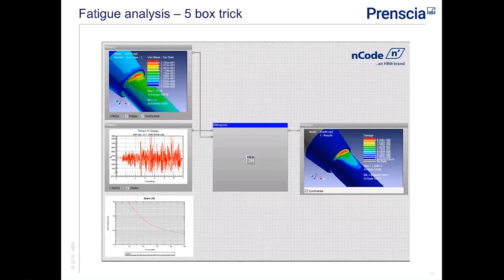And then, given those 3 types of input information, we can carry out a fatigue analysis, and then typically we look at the results in terms of contour plots of damage or life or tables. So this kind of process is pretty well established and trusted for metallic components.